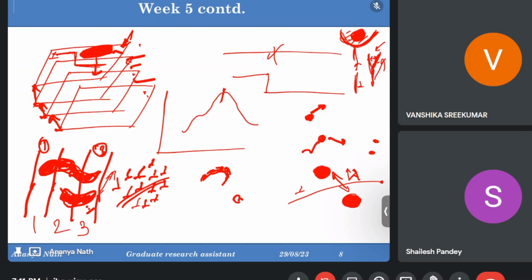They can cross slip very easily. So if there is a pile up of dislocations and in between them some stacking fault has happened, they can overcome the barrier of the stacking fault very easily if the stacking fault energy is high, and that means the stacking fault width is lower. So is it okay for you?